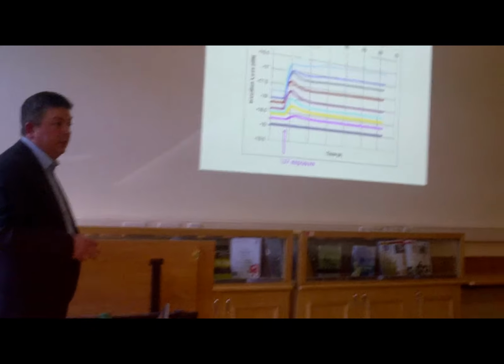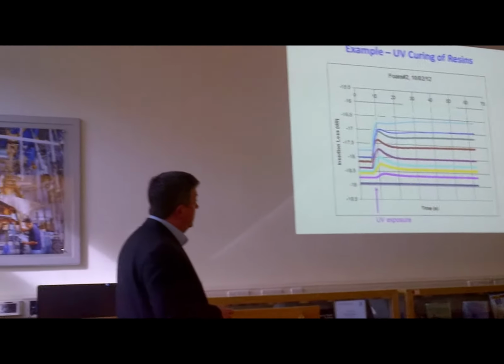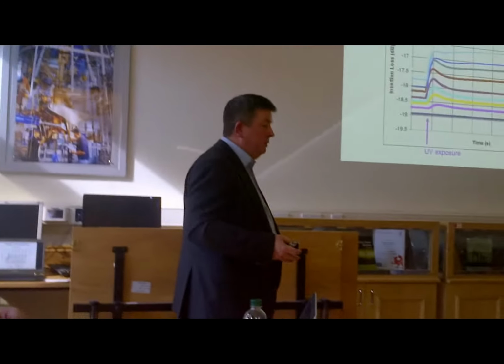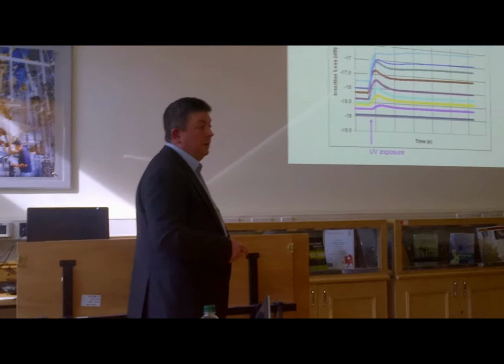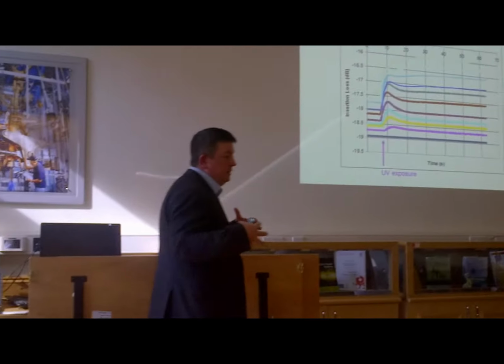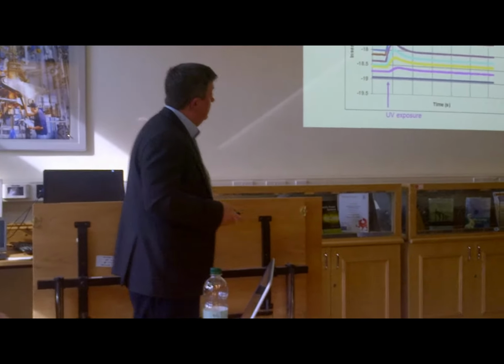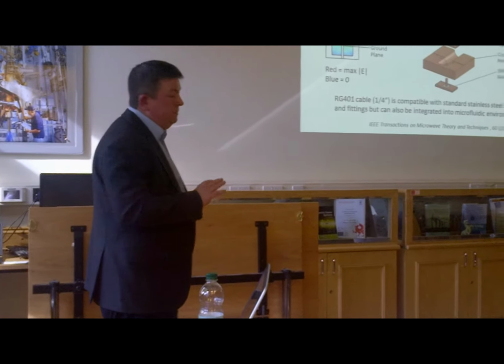This is another example of curing resins. This is UV curing of resin. So this is a resin foam, different compositions here. What we're doing is we're switching UV on here, and then we're looking at the dielectric property change of the subsequent polymerization process of the resin.